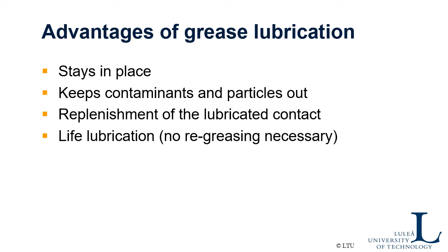And as I said, the process of replenishing the raceway contact is tricky, and it's problematic also, because when you rotate the bearing a couple of revolutions, you will soon squeeze out the grease from the contact. So you rely on the bleeding of the base oil from the grease, which is here and there on the cage and outside the raceway contact. So it must be replenished all the time, but it isn't replenished fast enough to create a full film lubrication.